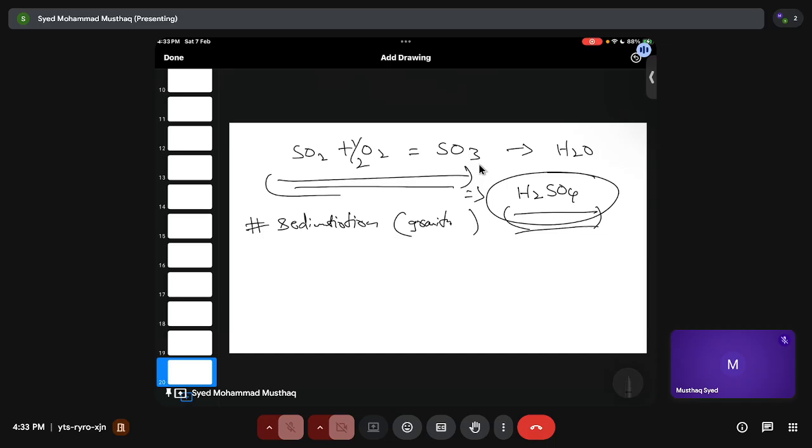So just a revision, okay? Sedimentation will depend upon your gravity, and gravity does most of the work. So it depends upon your size, density of solid, density of liquid, and also the medium in which it is, and whether it is turbulent, so it depends upon the Reynolds number.